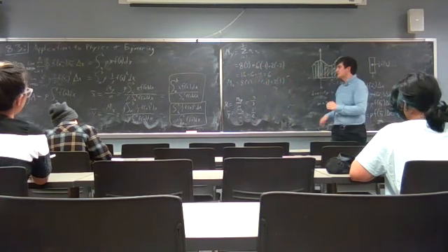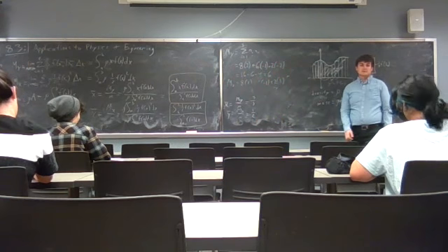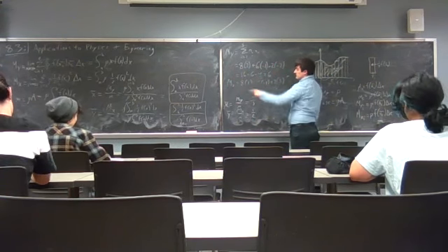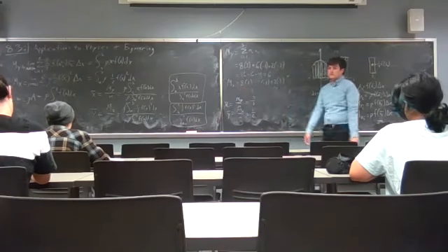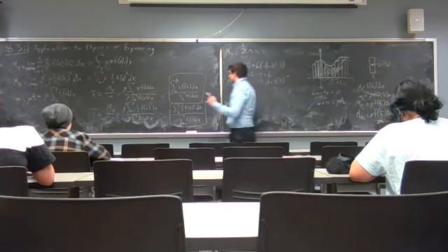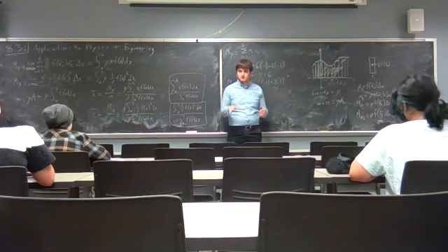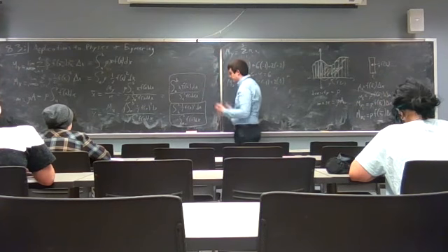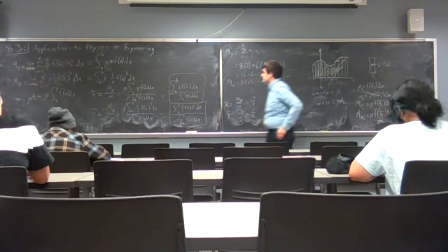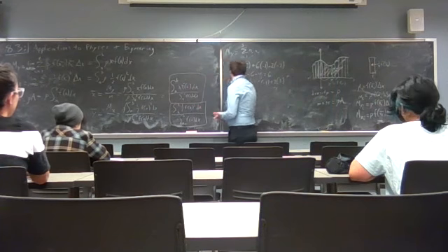Good. So if I want the centroid of this, I just have to evaluate two integrals and divide them, right? I do x times f of x for the x, and then I do 1/2 f of x squared. Now, keep in mind, and I know some people might be thinking to just divide the f of x's, you can't do that. They're inside the integral. We can divide the rhos because they're constants, but we can't divide the f of x's. So you have to evaluate each integral. But you could just do this one once, and then just evaluate each of these separately.